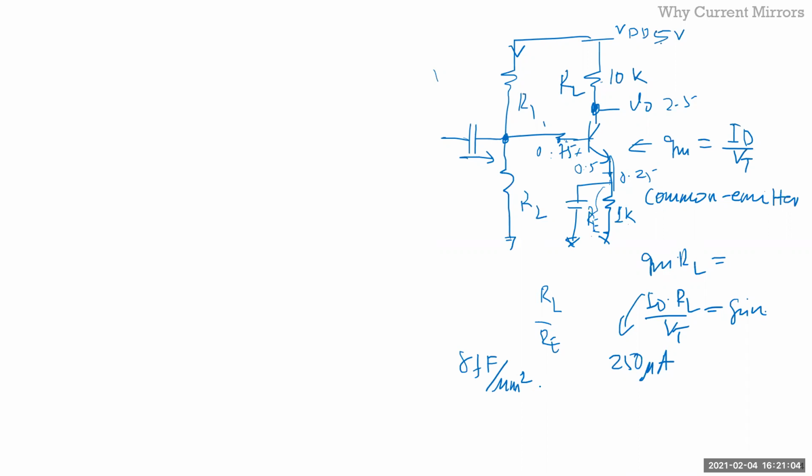If you go MIM, that's 1 femto. And if you go like finger caps, it's even lower. It's like 0.025 or 0.25 femtofarad per capacitor. So when you're trying to realize the picofarad, the size is just huge. Okay. So that's the reason you don't do this.